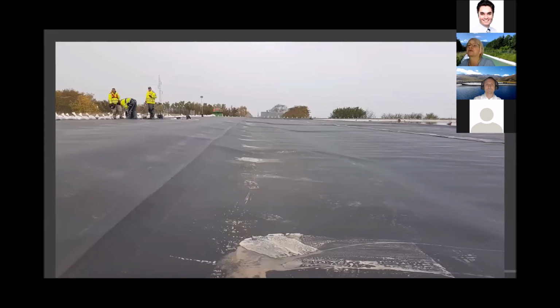You know the picture from the floating cover installation. This is the lower liner. The installation of these layers typically is done aside from the pond. So in sequences, it is then pulled over the filled pond after the sacrificial layer was removed earlier, which kept the water clean. And during this installation of the floating liner panels, it's also to be addressed that the service elements or the structures, outlet structures, have to be constructed aside from the pond already, and it has to be considered that they are set in the right place.